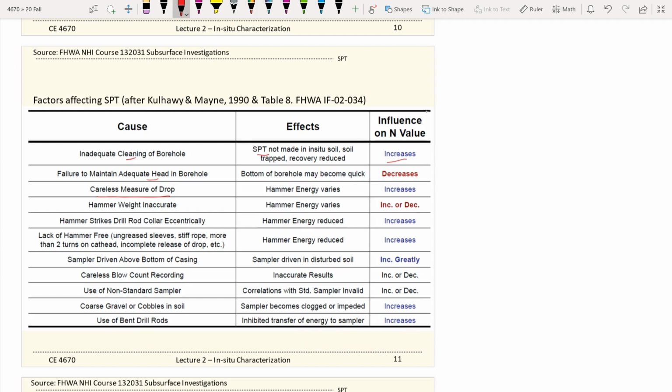So you need to make sure the contractor who manually raises the hammer every time maintains a constant drop height. If someone tries to cut corners and drops the hammer with a reduced drop height, you don't get the correct amount of compaction effort, and it will give you an SPT N value that may be larger than it really is.